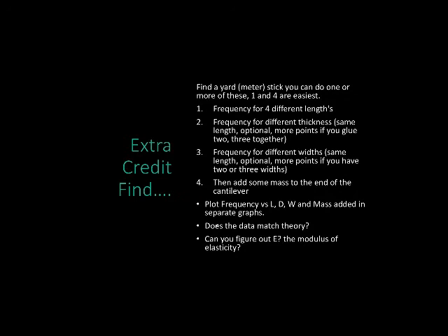that the thing vibrates. So you stop the video when it perhaps reaches the top of its motion, and then you count 1, 2, 3, 4, 5, 6, 7, 8, 9, 10, 11, 12, 13, 14, 15 frames, okay? And then it reaches the top again. So now you've gone 15 frames in one cycle. If you have 30 frames per second, you can do the math, and that's about 2 hertz. Okay, so it's going 2 times a second. If you're at 240 frames per second, then that's a lot faster.